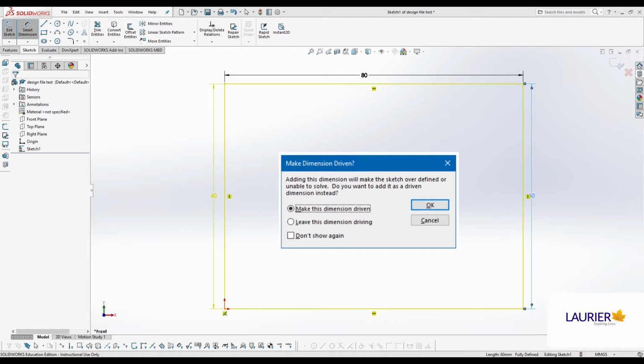So what we have here is something that has parallel sides on the opposite sides of it. If we look in the corners, we don't see any indication of 90 degrees. It just happens to be 90 degrees because these parallel lines are vertical parallels and horizontal parallels. The reality is what we have here is a parallelogram. And the property of a parallelogram is that the opposite sides have to be parallel and equal in length. As long as this thing's a parallelogram, we can't put two editable dimensions on opposite sides because one side's dimension forces the other side to have to be the same. Let's see what we can do.